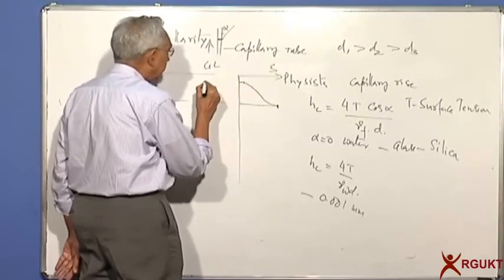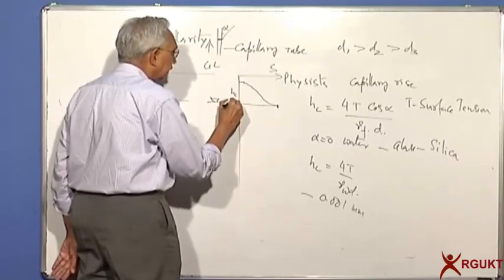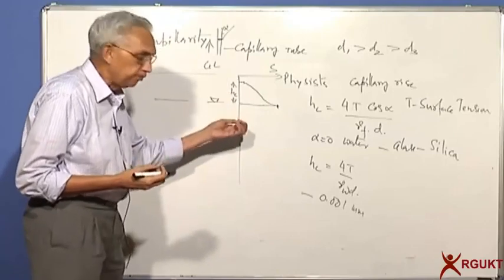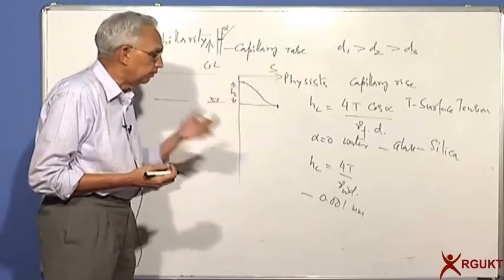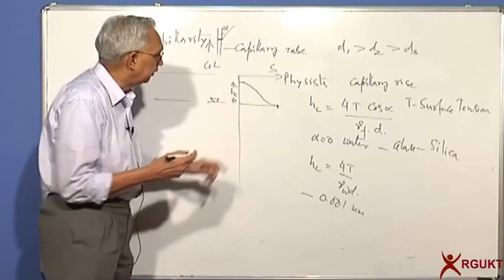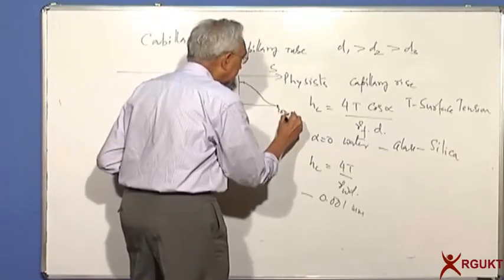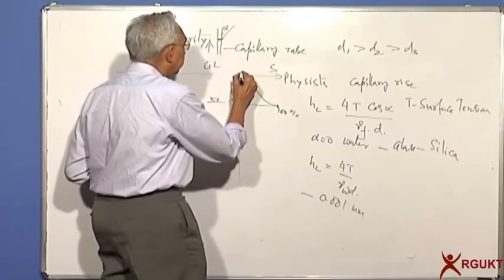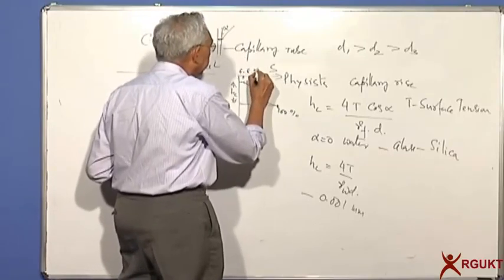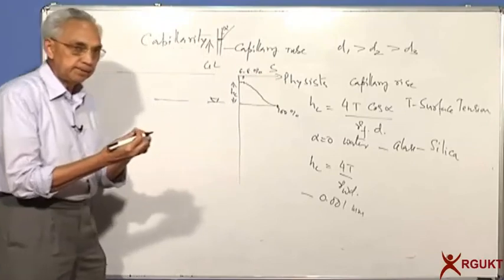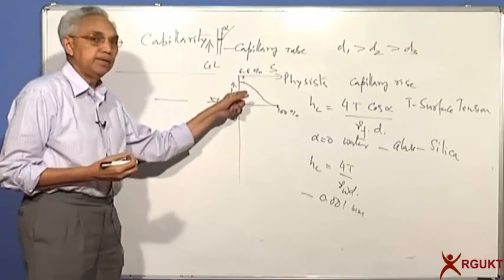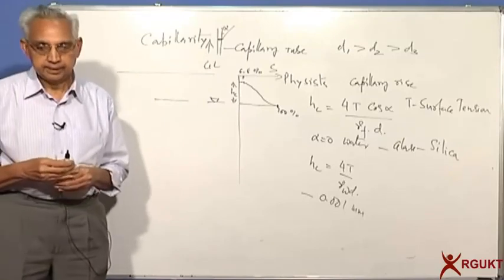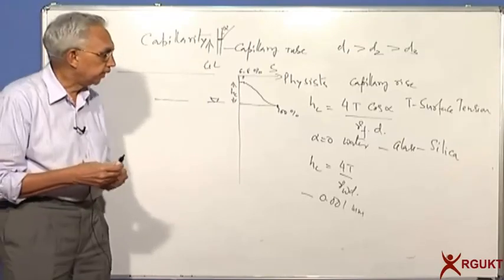Please remember, this is equal to the capillary rise. The capillary rise can be 0.5 meters, 1, 2 meters, depending on the soil. So that's how it varies. This is 100%, and this will be very small, what you can call hygroscopic moisture, 6 to 8%. So water can rise, but this will be under negative pressure. We'll discuss this at a later stage, and we'll talk more about it when appropriate.